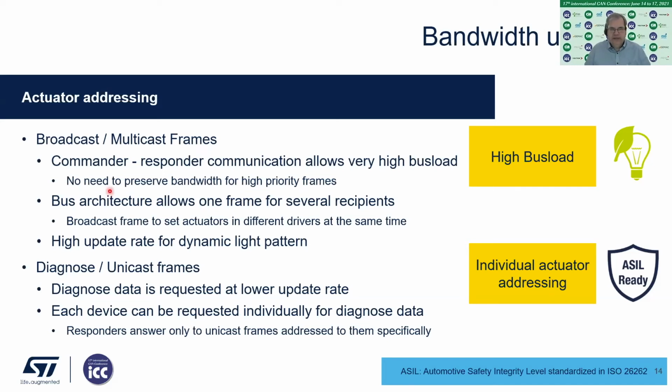So with 64-byte payloads, you can theoretically program within one frame the 8-bit PWM of 64 drivers for 64 LEDs scattered over several devices. Because you can send it to all devices at once, we can make use of that. That's why we implemented broadcast frames, exactly because of the bus architecture. And this allows a high update rate for the dynamic light pattern. Of course, with this kind of broadcast frame, you do not expect a response from the drivers, but you don't need it in all cases.